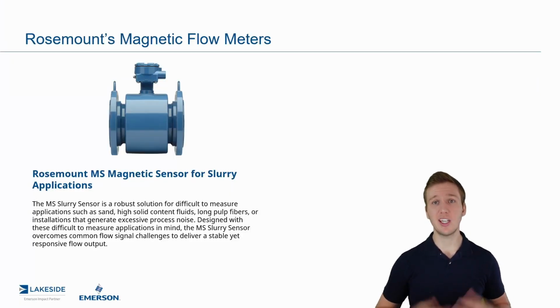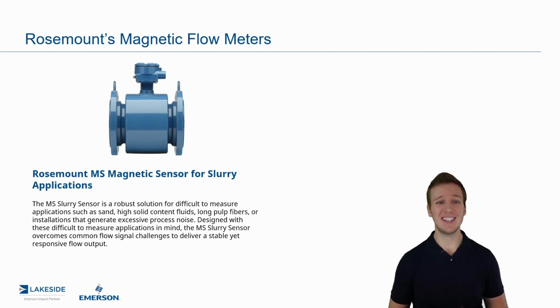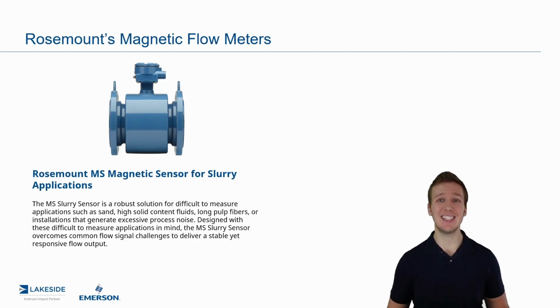Today's episode, we're continuing our discussion around Rosemount's magnetic flow meter technologies. In particular, we've been talking through slurry applications and the difficulty with overcoming signal to noise ratios. The reality is there's another challenge in these applications, and it's dealing with erratic or high variance in the raw data that comes from a magnetic flow meter.